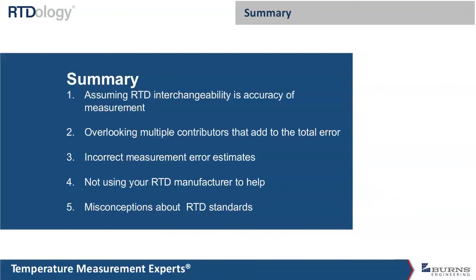And we need to look at all of the different error sources that come into play. We need to go through this, combining these errors. And, you know, if you are not comfortable with that and you don't have a metrology staff in the plant, call the manufacturer. I know I do a lot of assistance with this kind of calculations with our customers. Most of the RTD manufacturers can help. If they can't, again, you might want to think about going someplace else.